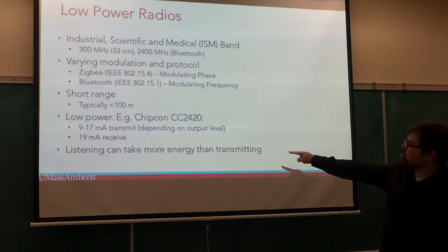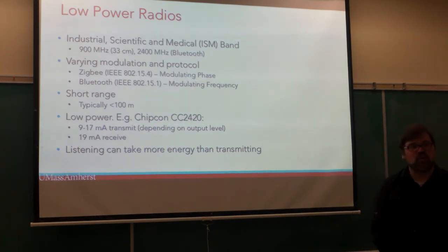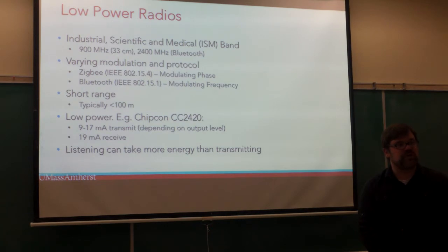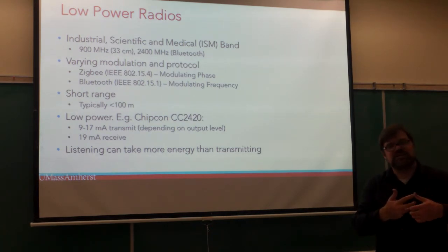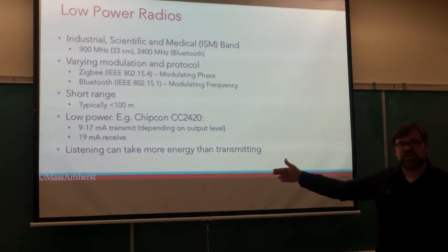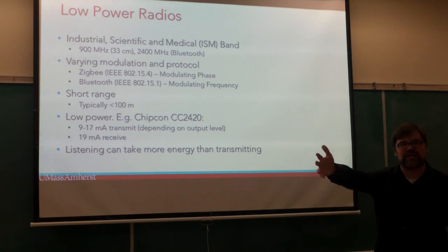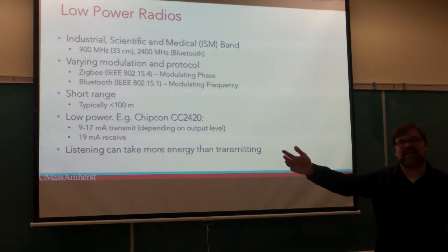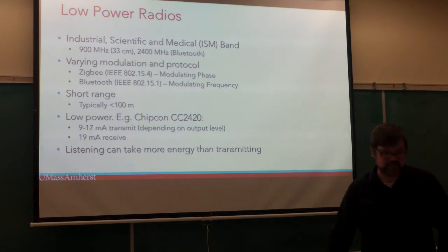And then the other weird thing is, sometimes listening can actually take more energy than transmitting, right? If the noise floor is very high, you have to do a lot of work to decode the bits that the transmitter sent to you. And the signal processing involved in receiving packets is sometimes more work to figure out what someone sent to you than just blindly sending something out at some power level, which costs less than trying to figure it out.